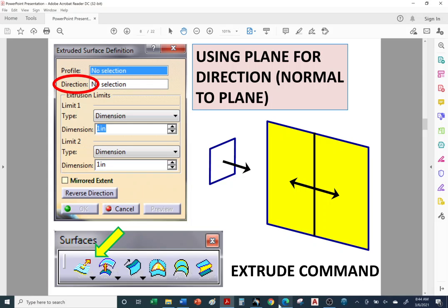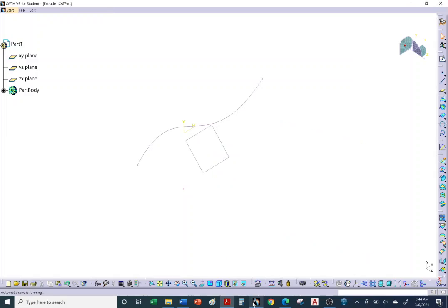All right, so let's go ahead and use the extrude command. Okay, so we're going to use this profile, and here whoever created this tutorial didn't use a geoset. They should have used a geoset. It's okay. It'll still work, but avoid creating geometry in a part body. It's not a good idea because it forces you to keep everything organized like a family tree. Geosets don't have to be structured like a family tree. It can be all over the place, like a big family reunion at the park. All the kids, grandchildren, grandparents, parents, great-grandparents can be all over the place, right?